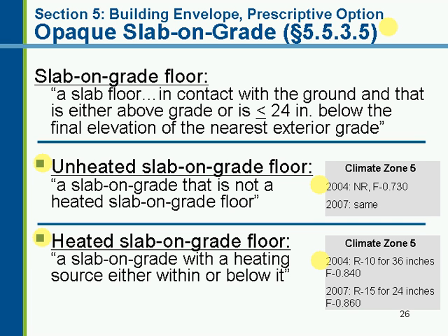So you're losing a lot of heat into the soil. So it would be a good idea to insulate under the entire slab, but the document does not require that. You only need the R10, which is approximately 2 inches of rigid insulation, for 36-inch depth, and that starts at the top of the slab.